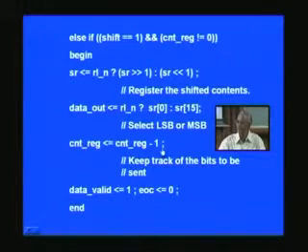But we are not going to check this status right now. We will check only later on. Right? We only take the action. Suppose the counter had been 1 instead of 16, 1 minus 1 is 0. So 1 bit is already processed here, and it naturally exits the entire always block, in the case where counter reg was initialized to 1. And so this is to keep track of the bits to be sent. So how many bits are remaining to be sent will be known if you just inspect the counter reg.